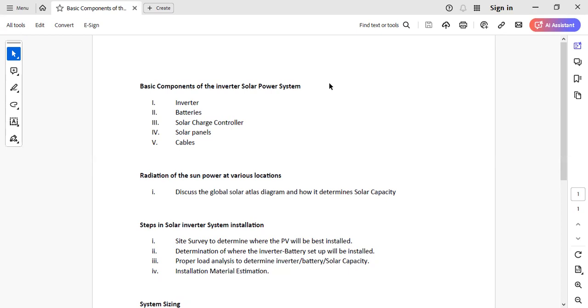And that is the same thing we do when we want to connect a 48-volt system. When you connect 12 volts, 12 volts, 12 volts in series in 4 places, you get a 48-volt system. But if you want to build a 12-volt system that has a lot of ampere hour, you just parallel them. When you parallel the four, you will have the same 12 volts, but 200 ampere hour in 4 places, which makes it 800 ampere hour.